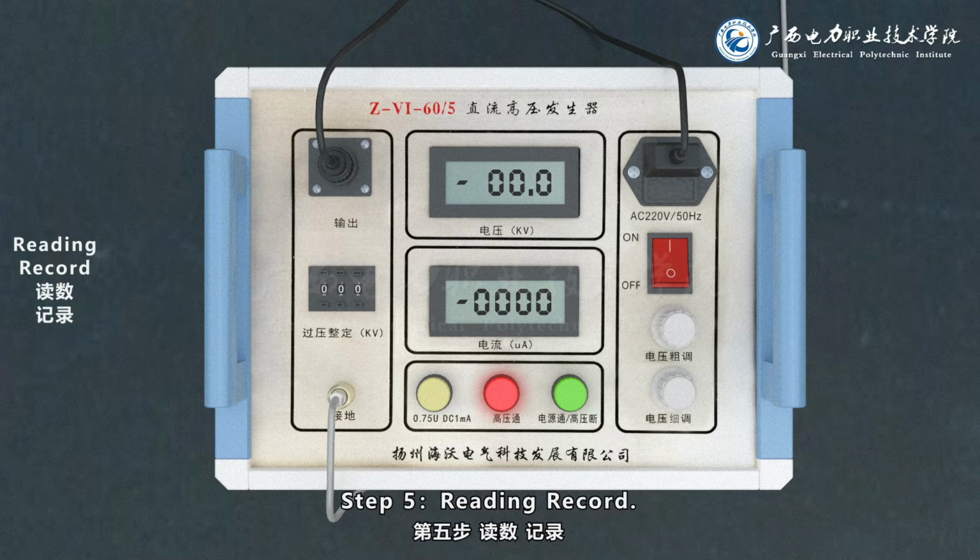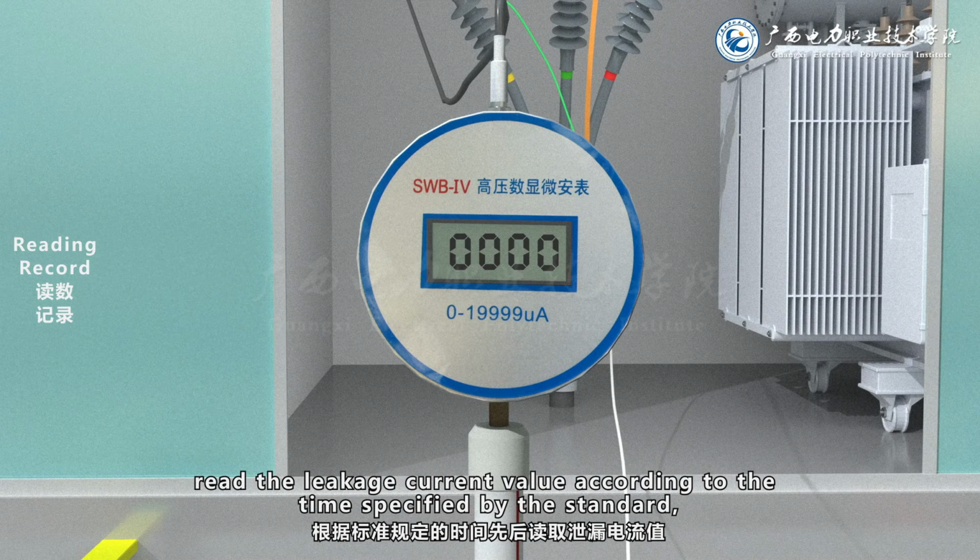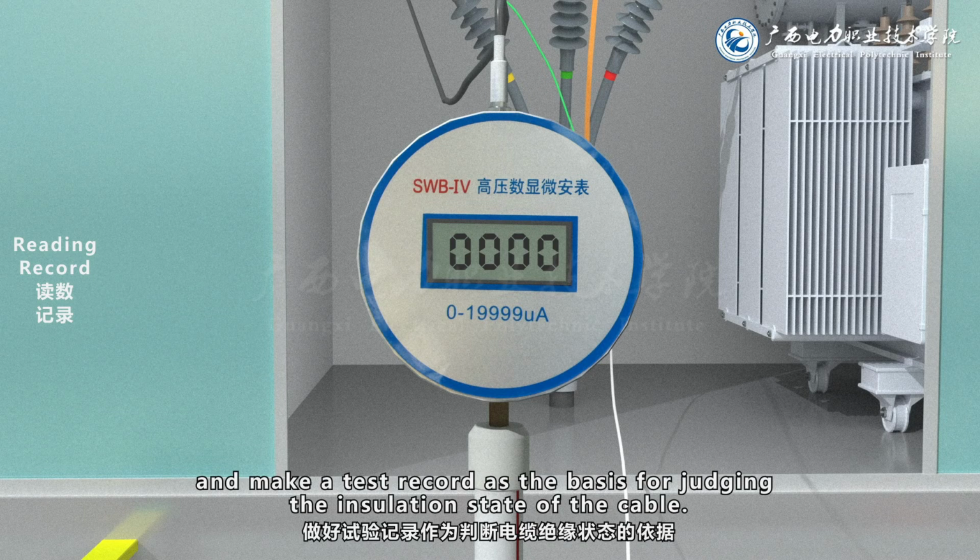Step 5. Reading record. After adding the standard test voltage of 35 kV, read the leakage current value according to the time specified by the standard, and make a test record as the basis for judging the insulation state of the cable.